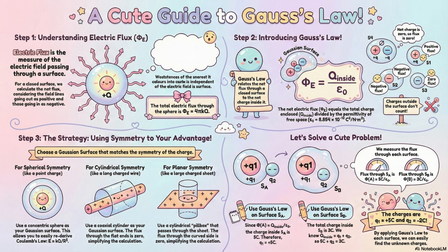That's a fantastic distinction. And the practical side of this is how we combine them. With capacitors, if you connect them in parallel, the capacitances add up. It's the opposite of resistors. You're effectively making the total plate area bigger. But if you wire them in series, the total capacitance actually decreases. It diminishes because you're effectively increasing the total separation distance between the outermost plates, which weakens the field containment.